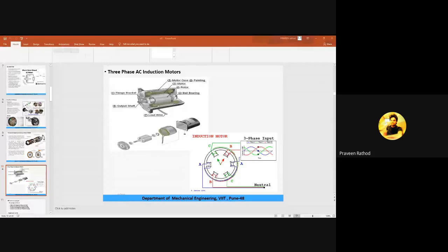Because the motor flux is initially constant, we can get maximum torque at lower speed. When the machine reaches the base speed, the flux weakens, and because of this the voltage remains constant, which results in the motor torque decreasing as the speed increases.